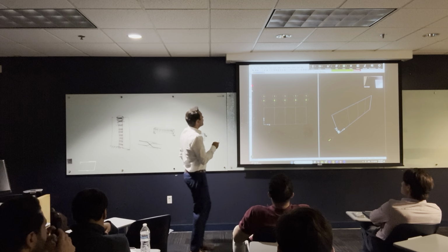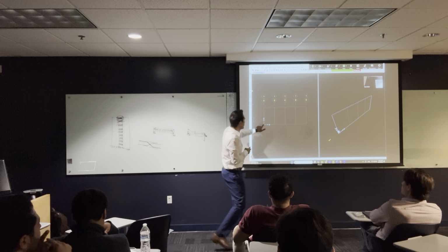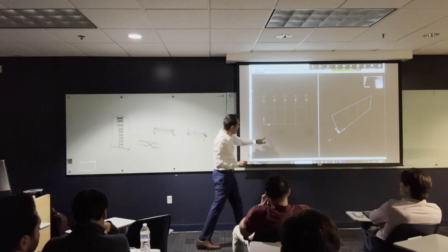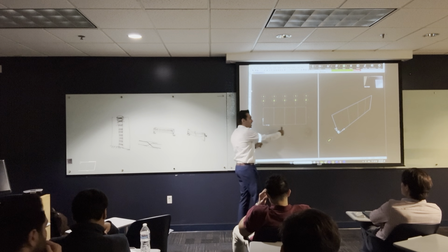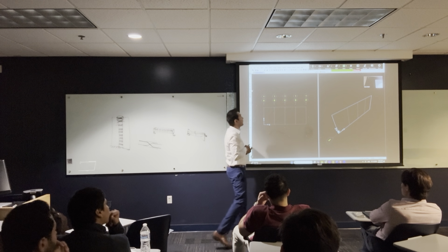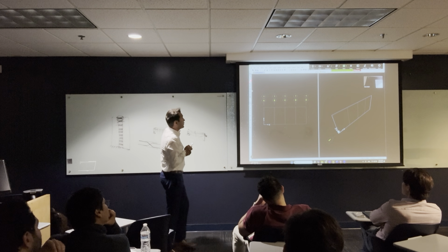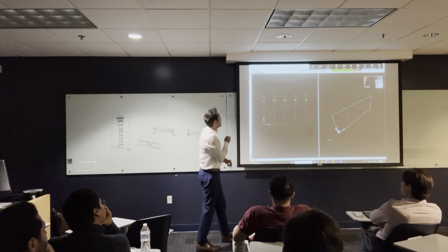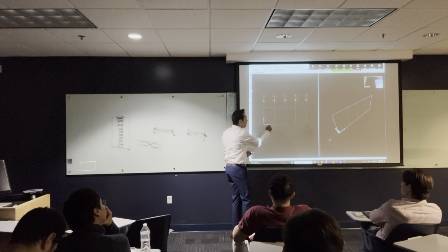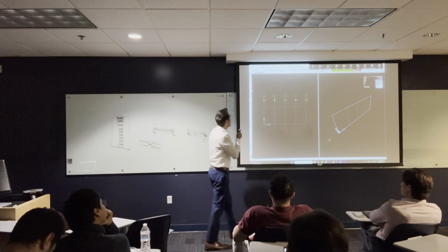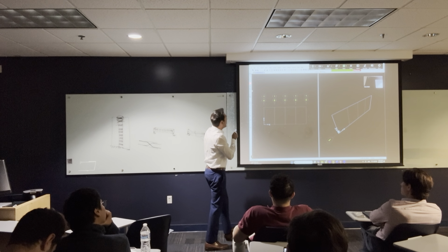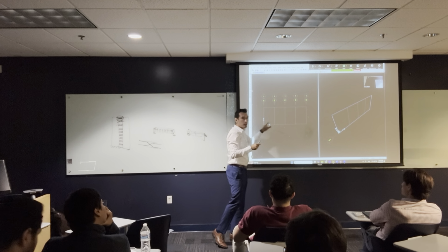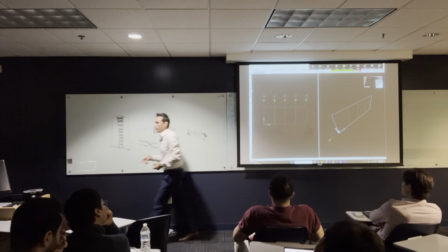So this one, if you want to draw a point, you just click on the point. It's going to draw a point. Sometimes you want to draw a frame member from here to here. So you just make a point here and a point here, and you draw a frame member between them. This is drawing a frame member between 2 points. This one is by one click: if I use the one that has a frame with a point in the middle and click on this grid, it's going to draw a frame in between the 2 points in the grid. So let's see the difference.